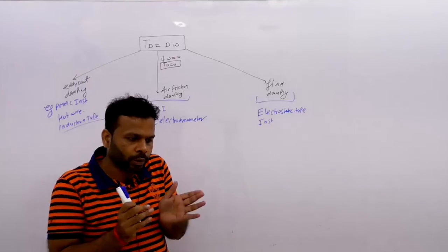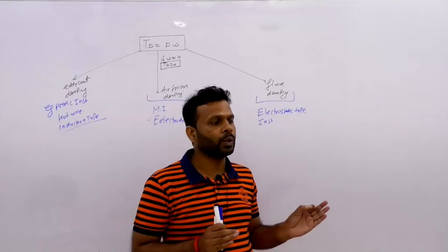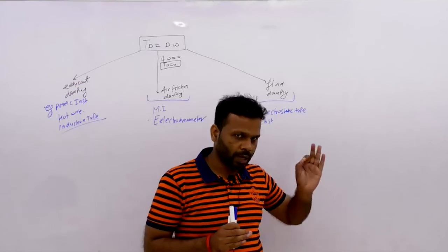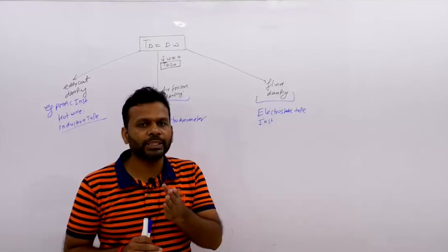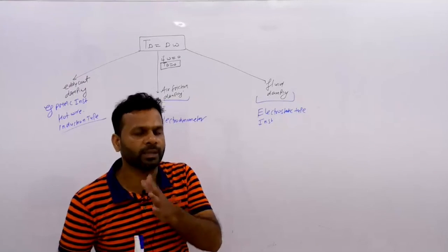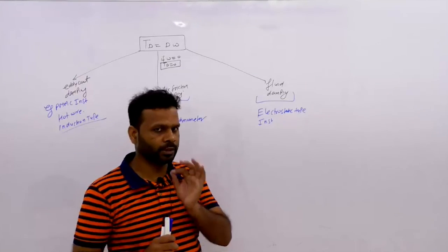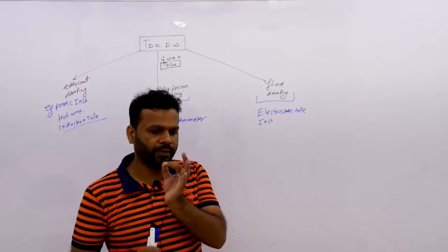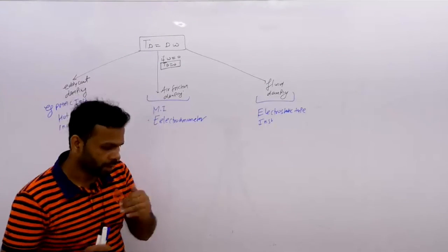Your core must have only one property, the magnetic property, that is low reluctance and high permeability. But your core shows an undesirable property, the electrical conductivity, so due to that conductivity it has some resistance.